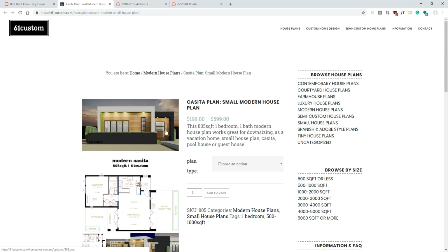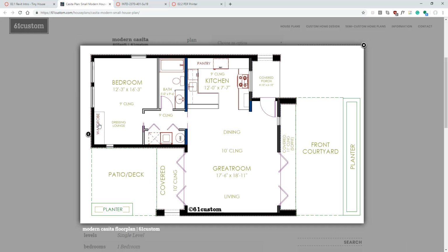And if we look at the plans right here, let me zoom into this one. It's saying 2x6 construction. And if I'm looking at this wall, this looks like a thicker 2x6 with stucco on it, right? Now, do these interior walls look like they're 2x6? No, there's probably a smaller interior wall type. Do we know how big those are? Nope, we don't. So that's up to us to put in what the interior walls are. So I'm just going to put interior wall, and I'm going to make this X because we don't know what that is yet.